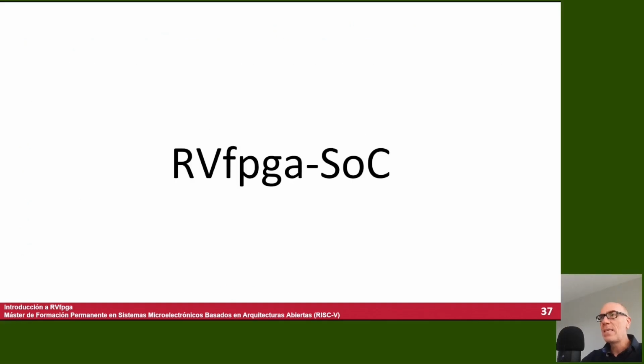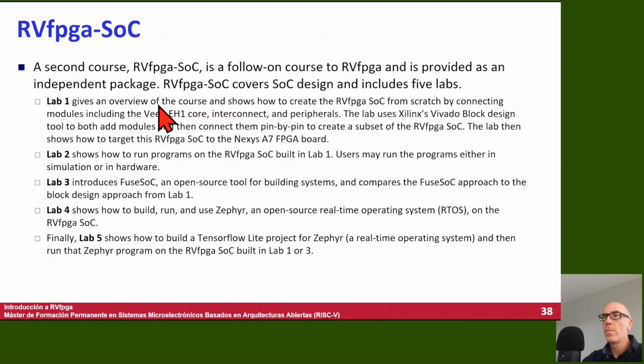The second package is RVfpga SoC. This package includes 5 practical exercises. The first uses Vivado's block design tool to create a simplified system on chip similar to RVfpga but with fewer peripherals.